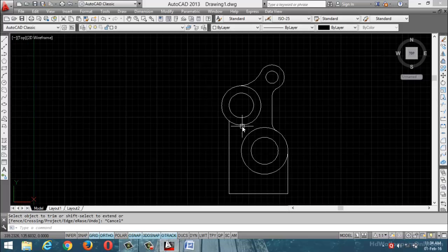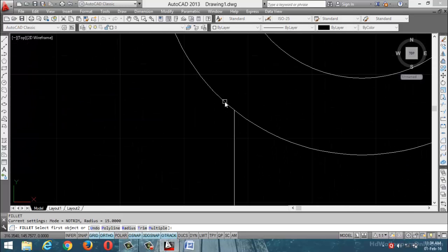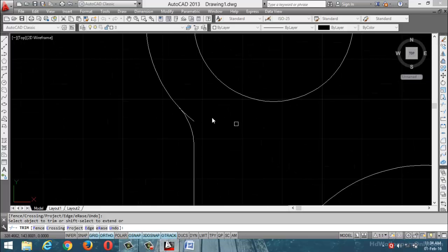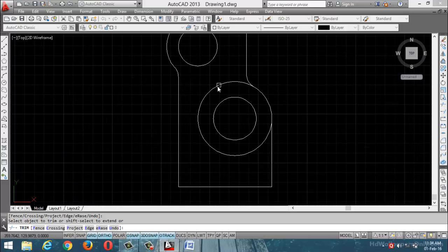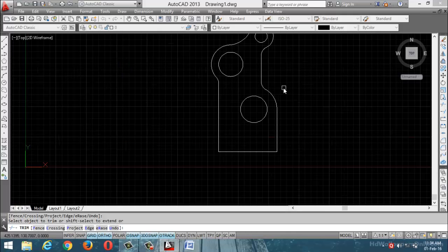Okay. Then again you can apply the fillet here. What is the fillet value? 14. Radius changes to 14. This one to this one. Apply the trim operation. Okay. Again next one. This one. Now again this one also. This entire circle is also a reference for this arc. Again you can trim this one also. Okay. Now this design is okay.